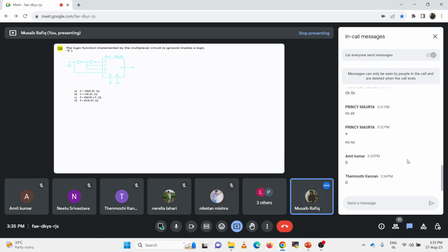So I see some of you have solved it. I was just looking for this BCD subtraction. There are 2, 3 methods. One of the methods is the ones complement method, where you take the ones complement of the subtrahend. Subtrahend means the number you want to subtract from another number. So you take the ones complement, then add.